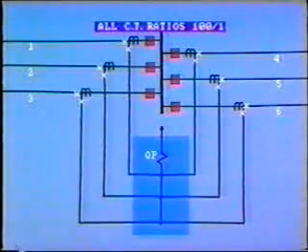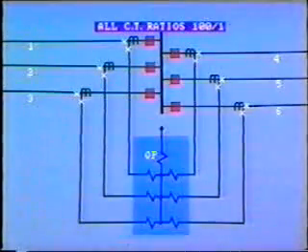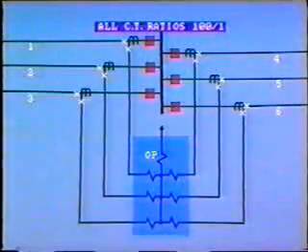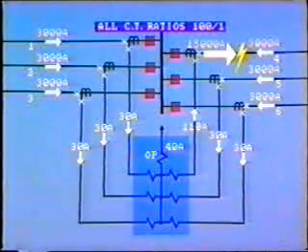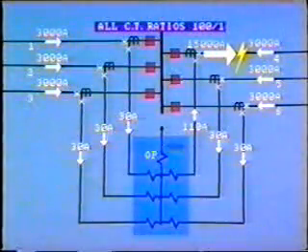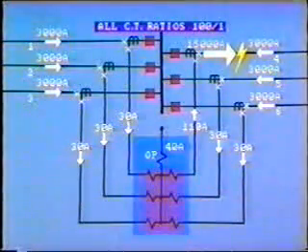One method to improve the reliability of operation during this transient period is to utilize a differential relay with multiple restraint coils. In the example shown, they would be connected like this. Applying the same numbers as before, we see that we have 40 amps passing through the relay operating coil, but this is opposed by the restraint coils.